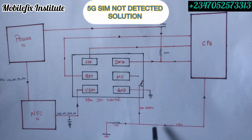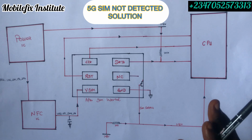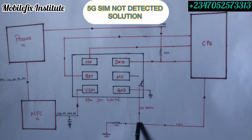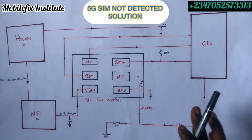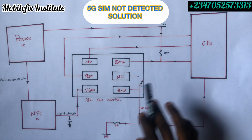Now when you insert, how will you test this line without owning the phone? When you insert your SIM card tray, it's going to disconnect this line from ground while your phone is still off. Then you test this on diode readings, because you have disconnected from ground. You get the value from your CPU side. You get value. That's how to test it.